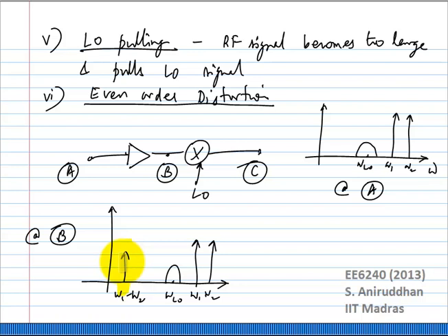The thing is, we have actually managed to solve it because of the signal processing power we have, which is we are actually able to calibrate out the DC offset. We're able to measure it ahead of time, calibrate it out, and then we can go ahead and apply the DC offset correction and then go on with life as usual, right? That is the only reason why we have actually been able to use the direct conversion receiver with most of these modern receivers. Otherwise, we wouldn't have been able to.